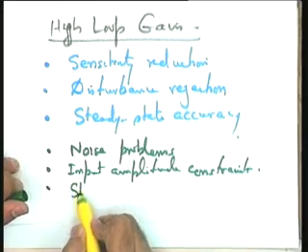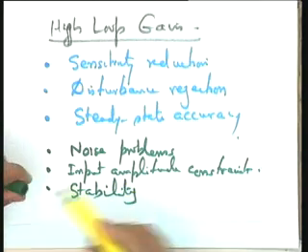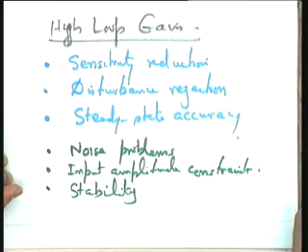And the stability problems you will see, that is the transient response or the dynamics problems, that we will see later in detail. That is, higher the loop gain, more prone is the system to instability. You will see there, higher the loop gain, more oscillatory the system becomes, and a more oscillatory system can become unstable, and therefore high loop gain is limited from the stability requirements also. So it means the design is a trade-off between the various design requirements we have seen. The various design requirements have to be simultaneously met to see that the overall control objectives are satisfied.